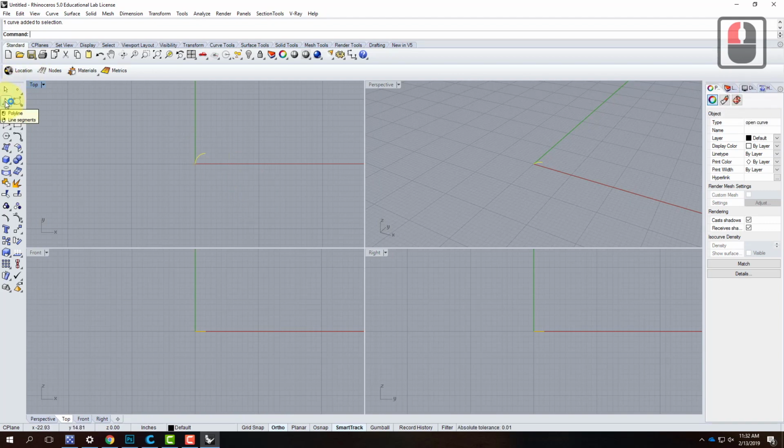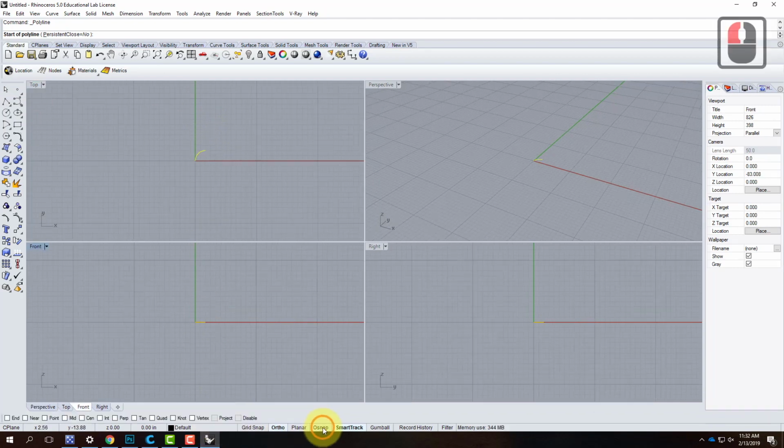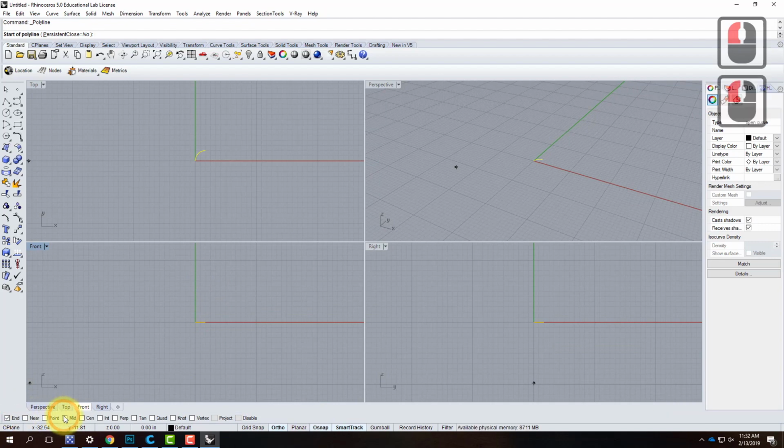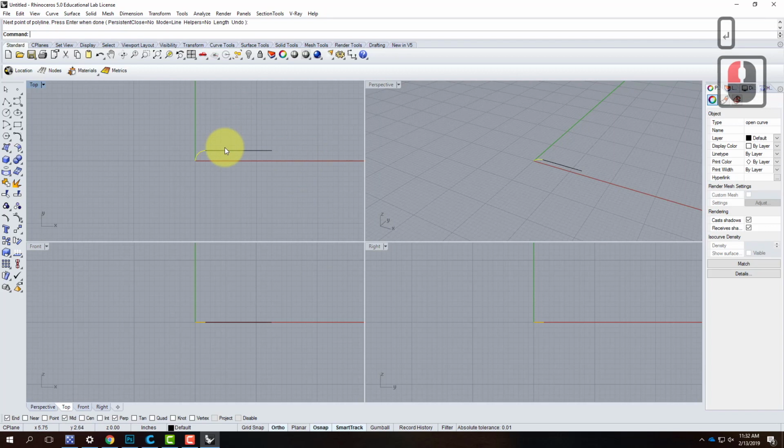I'm going to continue and go to the Polyline tool. I'll snap to the end. My snaps are not currently on, so I'll come down here, turn on Object Snap, turn on End, Mid, and Perpendicular. I will snap right there to that end, and I'm going to draw a line that is 13 inches. So I'll go ahead and type 13 and then enter. Just the direction. There it is. I'll press one more enter to finish, and now I have that line segment there as well.